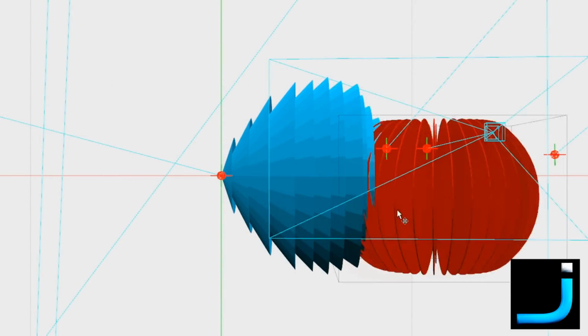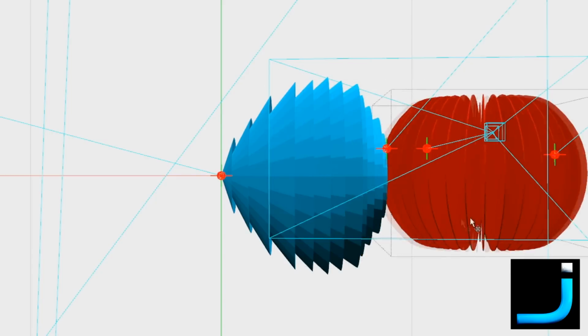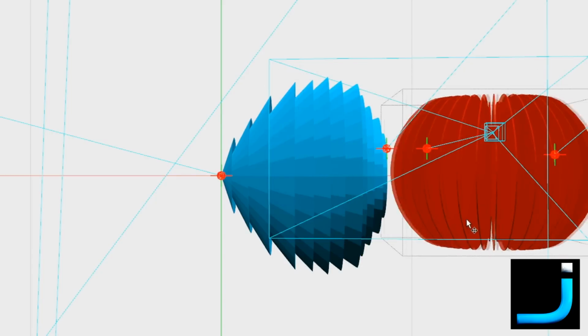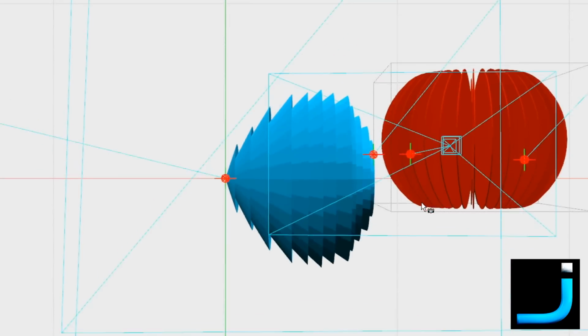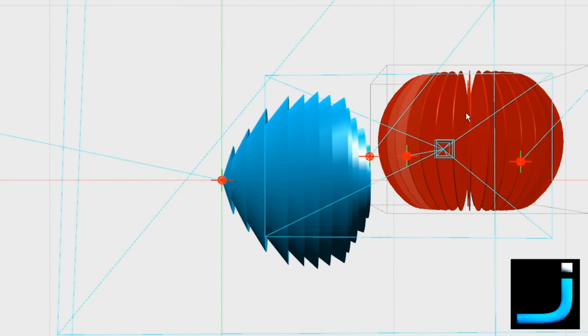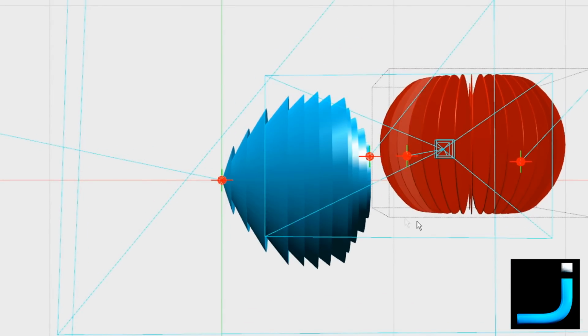But if you're in this vicinity in front of the circularly polarized 8 decibel antenna, you're going to get a rock solid signal no matter where you are around it, despite that 3 dB loss. Because again, if you compare that to the linear differential, that's 26 decibel loss.